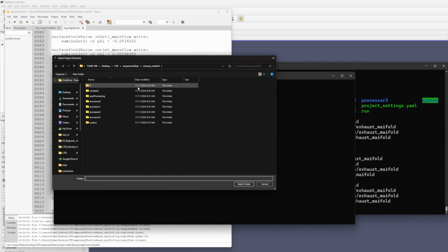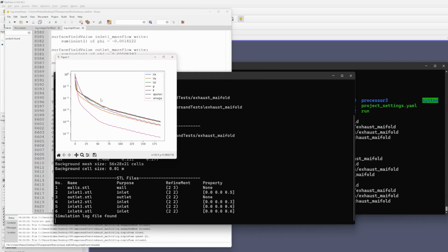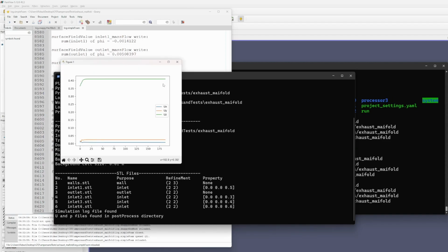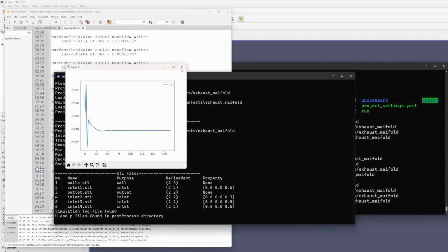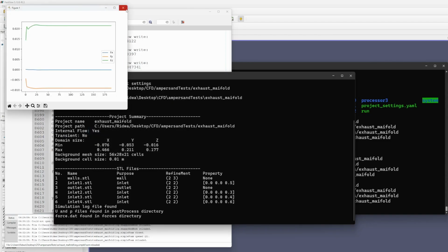So you can use tighter convergence criteria. So I will show this again. It's a little bit oscillating, but it's still dropping, but the flow variables are not oscillating anymore. So I think this is a good convergence.